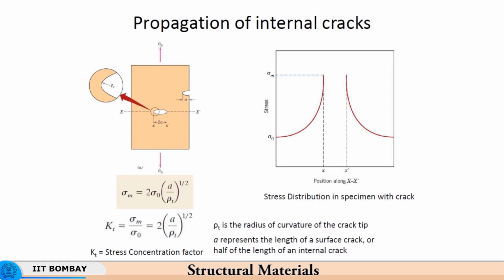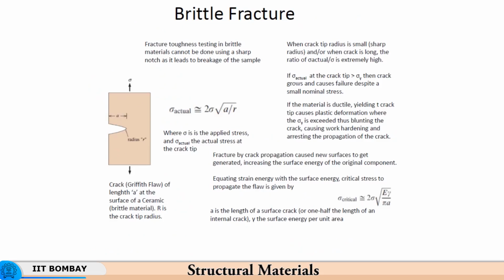With lesser stress concentration, there is better distribution of stress all over, and therefore the crack does not propagate. So, the crack propagation gets arrested, and this kind of thing is perfectly acceptable. You can still use the component even in the presence of the crack, because the crack is no longer propagating.